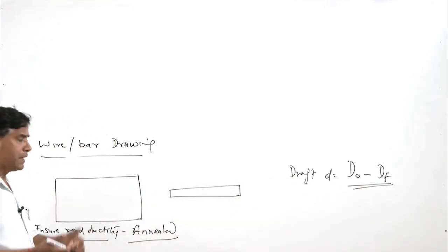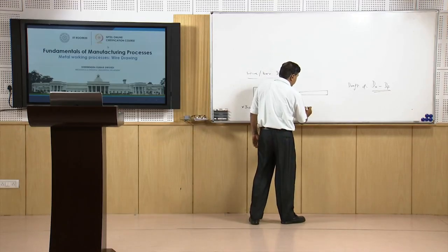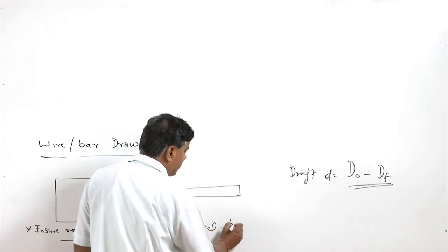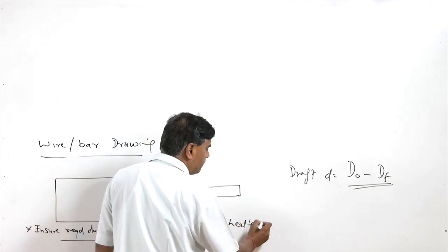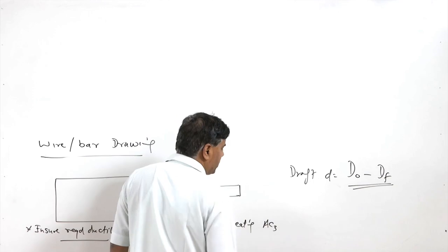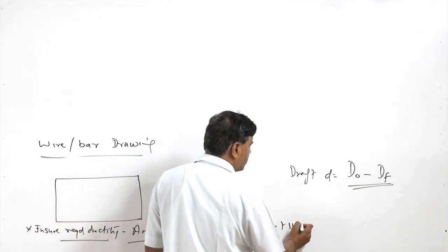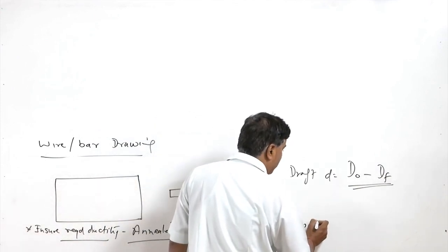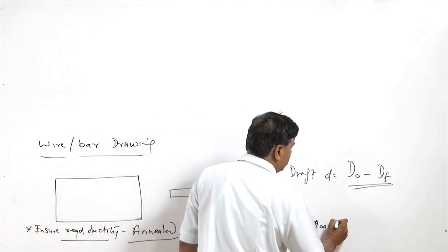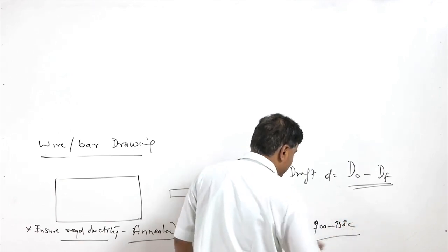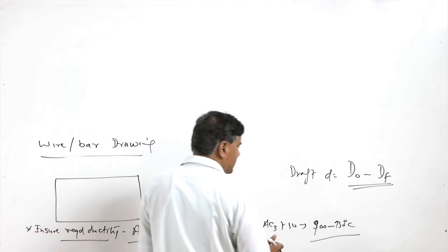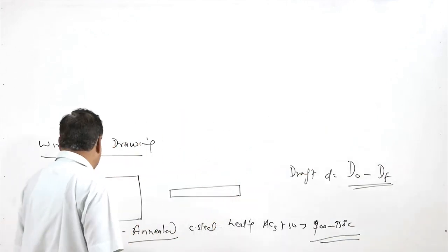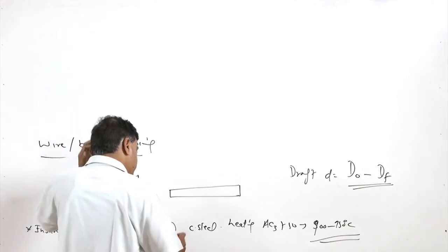Depending upon the kind of metal system, for carbon steels, annealing is carried out by heating the bar above the AC3 temperature plus 50 degrees. Say depending upon the carbon concentration, it may be 900 to 950 degrees centigrade. Depending upon the carbon content in the steel, there can be a very wide range for the annealing, which will be used for inducing the ductility.